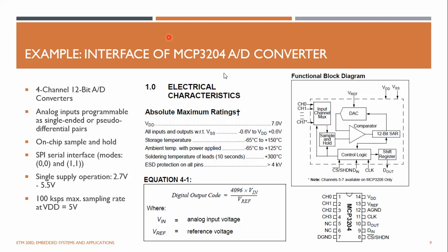For example, if your VDD is 5 volts and you apply from an AVR microcontroller, your clock voltage should not go beyond 5 plus 0.6, which is 5.6 volts, the maximum voltage that should be applied to this pin, and the lowest voltage should be minus 0.6, right?